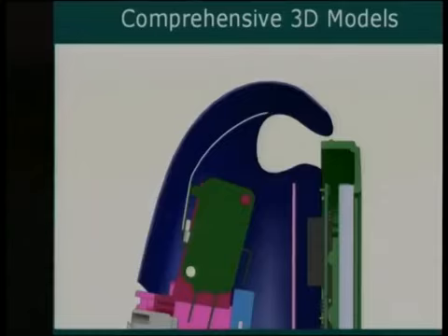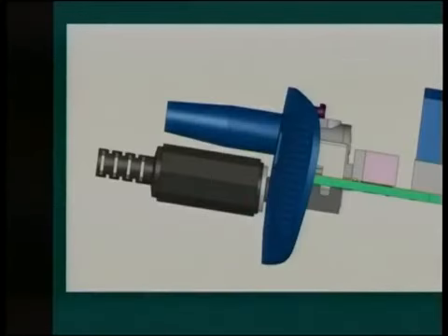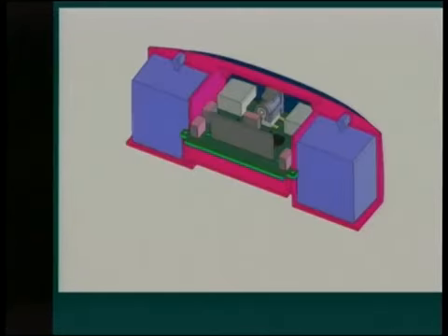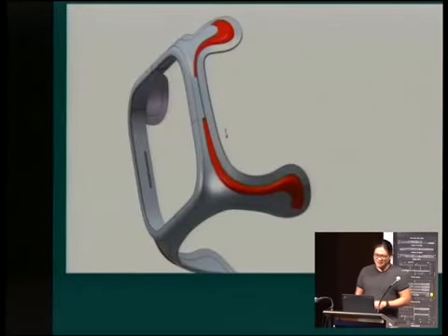So every design that you want to manufacture starts with a very detailed 3D model. We would model the circuit board and the parts on it, all the connectors, all of the holes, cross sections, the clearances, everything would be done in a 3D model environment. It's very important to make sure your connectors don't collide before you actually make your product. It's sort of unfortunate when they do, so we would take time to make sure that's okay, make sure the LCD doesn't fall out, make sure the speaker boxes sound good and are the right size and so forth. So we did a lot of modeling and CAD work.